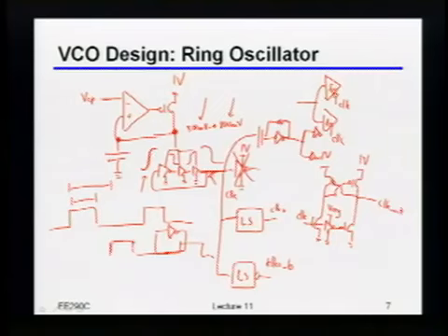Okay? Yeah. Well, some of the VCOs I remember seeing in the past are fully differential. Okay, we're going to talk about that in 1 second. There are VCOs that will give you what should be differential signals, but by the way, even there, they will mismatch, right? Again, we're going to draw that in just 1 second. But in general, there's no perfect way to do it. There's only, let's say, getting it close enough. And then if you really, really care, you'll tend to end up building what's called the duty cycle corrector. So you'll actively try and correct those phases. Okay?